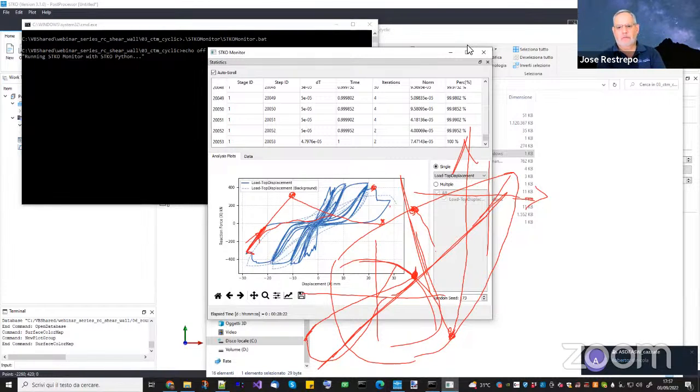So if your reinforcing steel is rate dependent, you should be able to reduce your damping quite a bit. The rate dependency of concrete is not as important because the strain rates in concrete are much lower if the neutral axis depth moves towards one side. But those in steel can reach 10-20% per second, and those are not negligible at all.